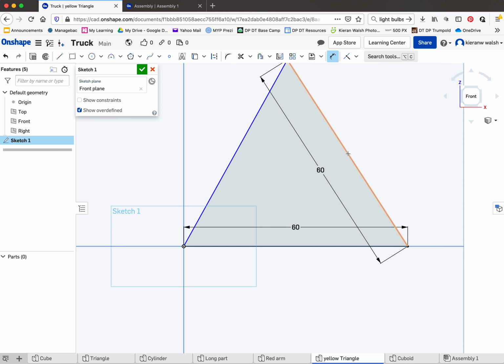Choose the dimension tool, click on that edge, move the cursor down. You'll see this dimension appear. It can get a bit confusing, but you just move down until you reach the other line. It turns orange. Click once, and you'll see you can drag away a dimension. So all I should need to do here is change one angle to 60. Because that was dimension to 60, and that's dimension to 60, and you've made this angle now 60, everything else should be correct.